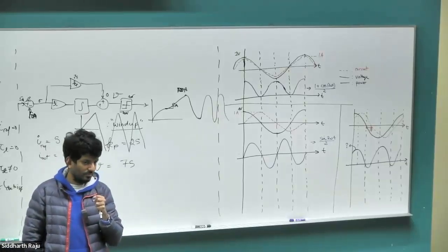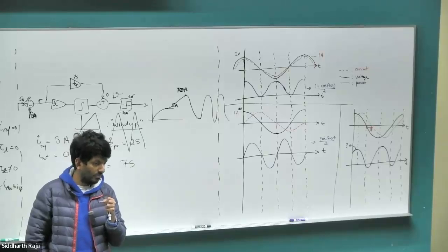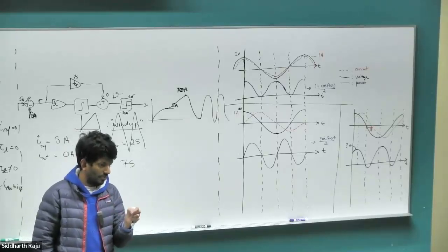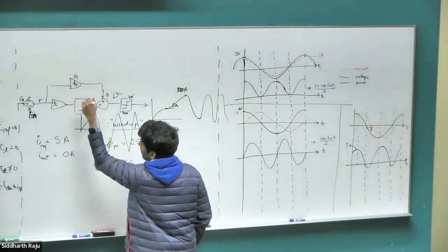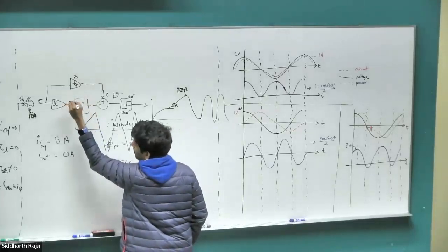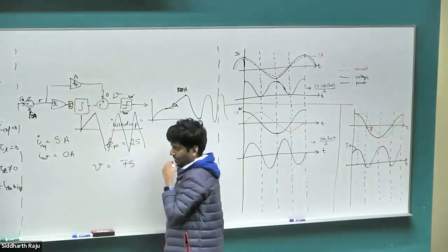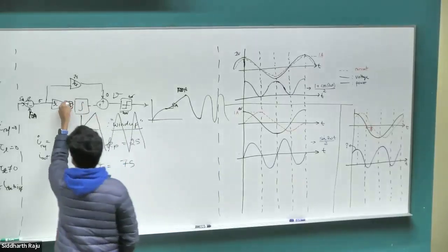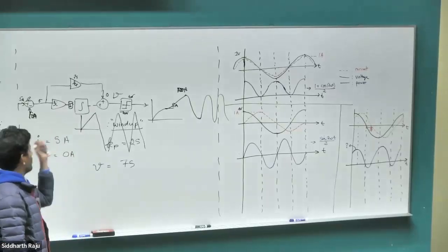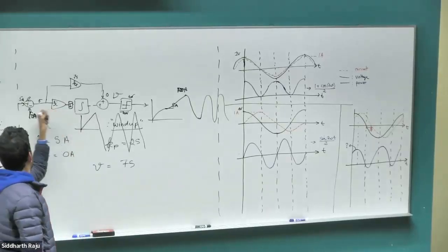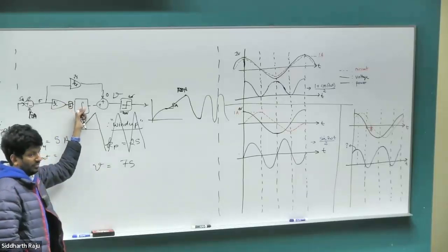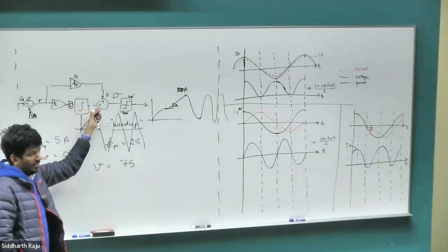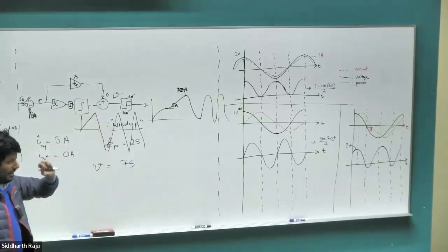Any ideas? Put a saturation here, like the line of your KI. The line of my KI. Do I just put a saturation here? Yeah. That would still be a problem, right? Let's say I put the saturation at 5 ampere, which is my motor limit. 5 ampere times KI. So once I have that error 5, it is still going to be a constant 5 input to the integrator, which is going to keep on winding it up further. You're on the right track though.